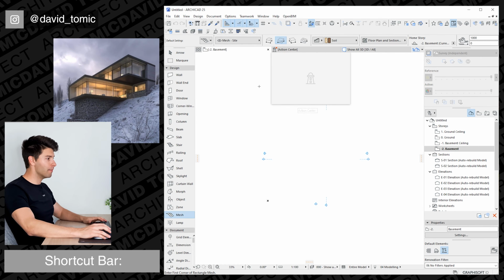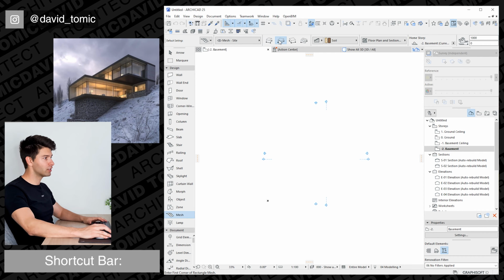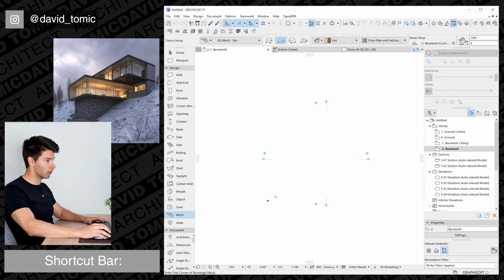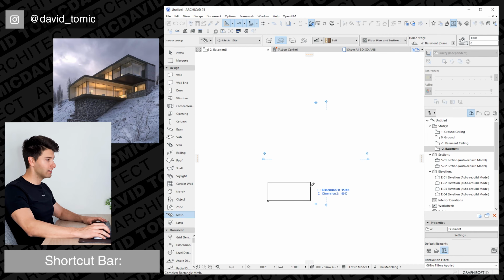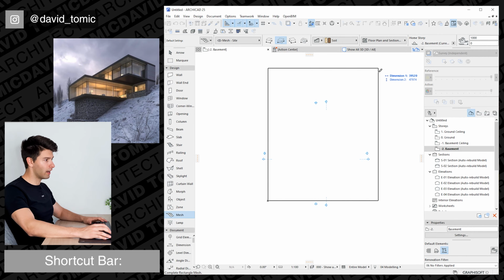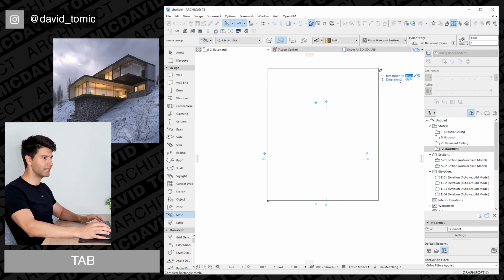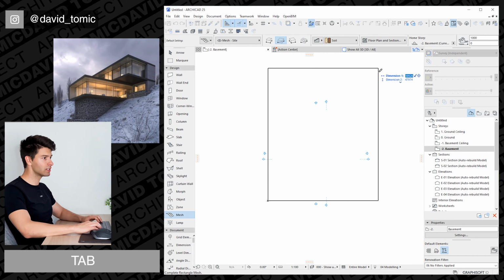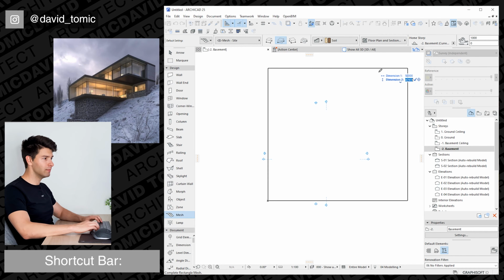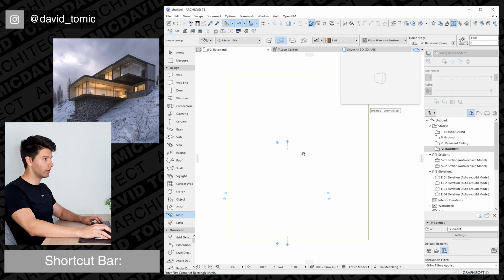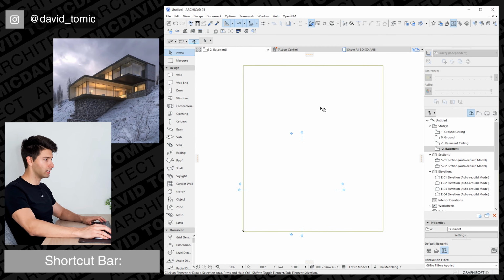So starting with our mesh straight away, we have our mesh site. I'm going to draw a simple box and all my layers appear to be correct. So let's start at the intersection of 0, 0, 0 on ArchiCAD. Let's draw a relatively big square so we know what we are working with. So if I press the tab key, it's going to activate my dimensions. And let's say we want to have that at 50 meters wide, and we probably want to have that at about 60 meters long. So we have a nice rectangle starting straight away.